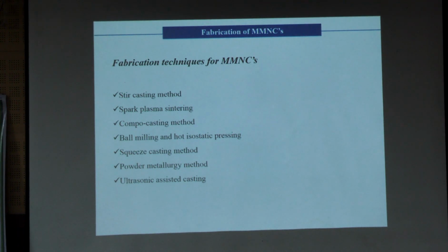But the basic procedure is the same. We melt the metal and we mix the nanoparticles at some temperature, and we use ultrasonic vibrations to mix thoroughly.